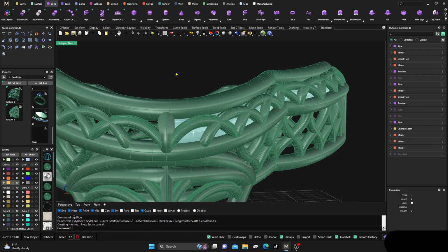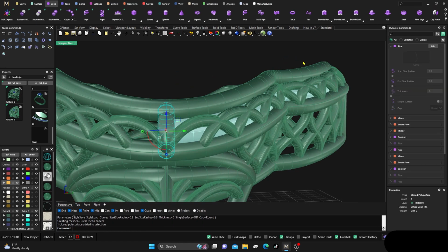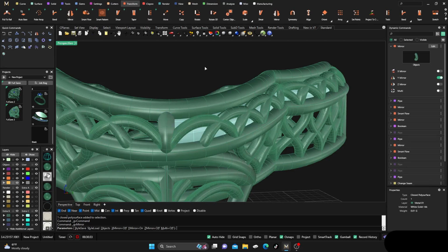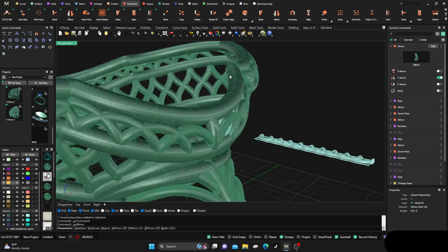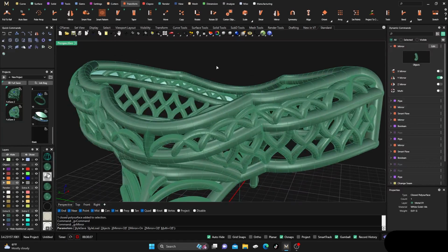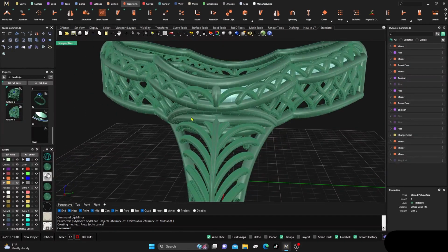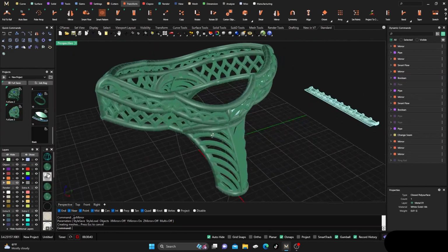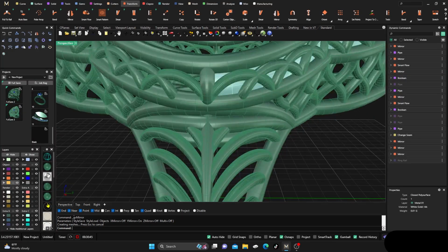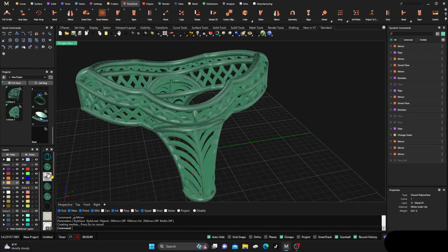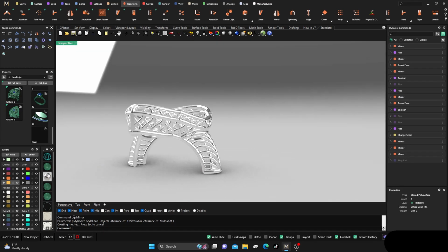And we'll hit enter, and take that and mirror it over to our other side. No X, Y or anything, just the Y, and it should add this one right there, and hit enter. So there we go. So it cleans up that area, right, and keeps it dimensional. So now we can turn this back off, right? And we've got this going on so far.